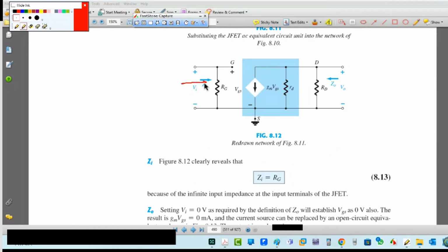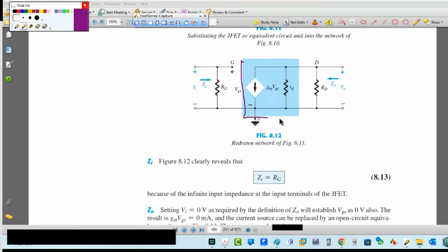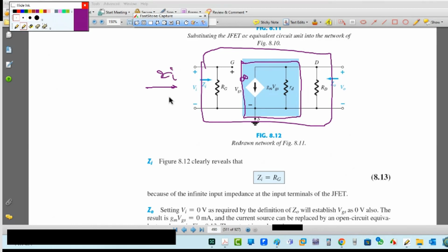See, I have here ZI. Here we have a value. Take care. Before we said ZI for the transistor, here ZI for the configuration. Clear? ZI for the transistor is infinity. For the configuration, we have a value. Clear? This is very important. Those are small tricks. Repeat again. This is the transistor, ZI is infinity. This is the system, we have ZI. Repeat or clear?